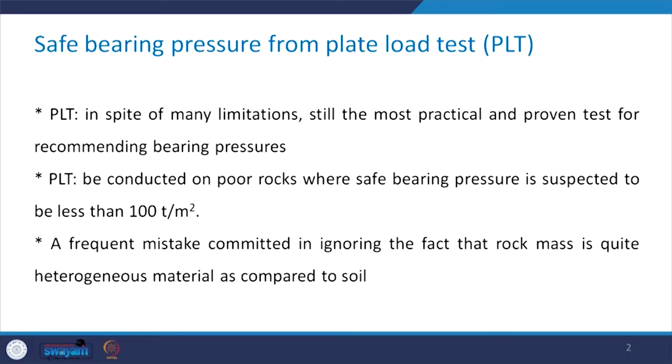The procedure for carrying out this plate load test on rocks or rock masses is exactly the same as in case of soils. Although the plate load test has many limitations, it is still the most practical and proven test for recommendation of bearing pressures.